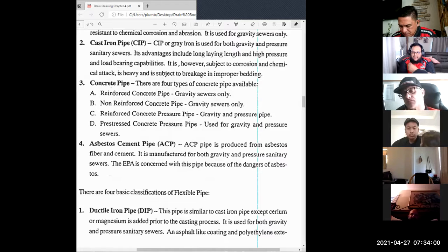And even when cutting into that drain, we use a wet target saw. You don't want to beat on there with your grinder. It is electric or battery, and you want to have some kind of water moving as you're cutting through that pipe. So we use our target saw with the water and everything, and of course everybody wears a mask. And that's one way we deal with it here.